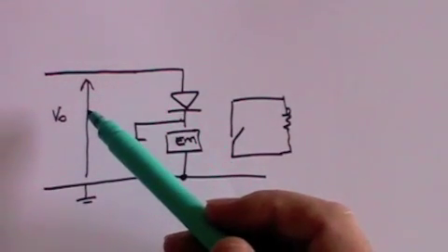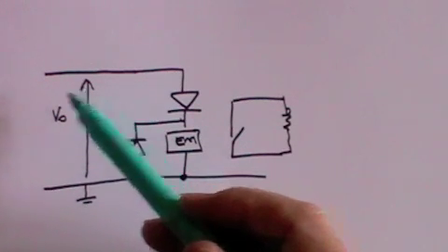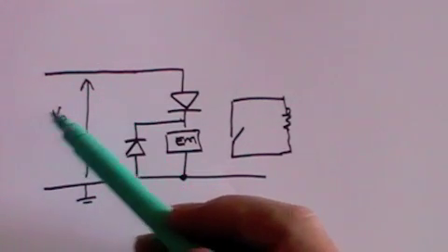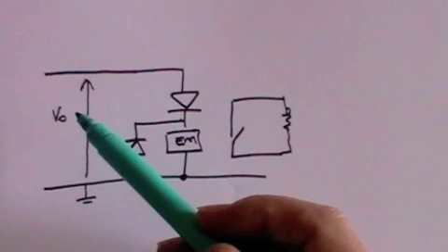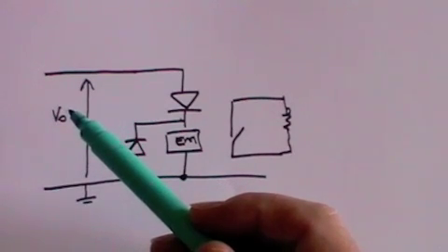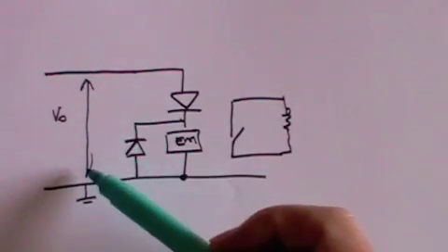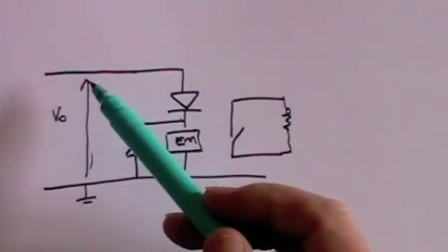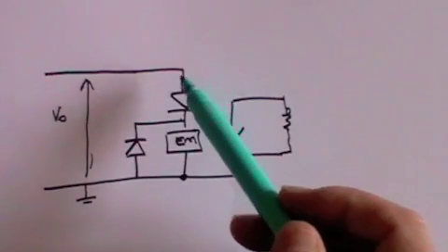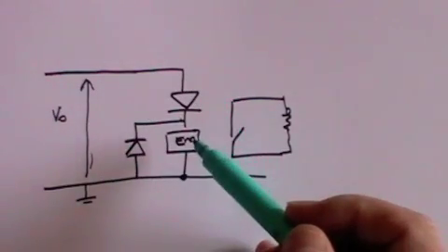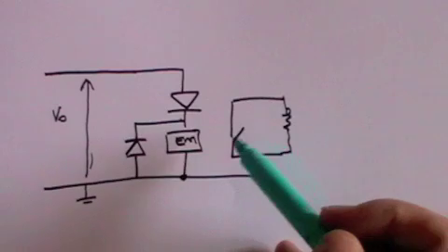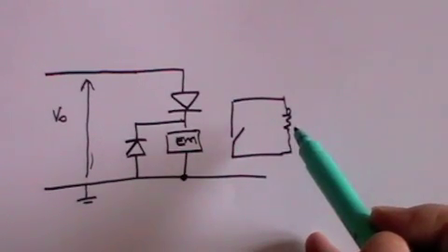But as soon as darkness comes and the room gets dark, then the sensing device will change its resistance such that the combination of that plus the operational amplifier and the circuitry reverses the polarity from a negative voltage to a positive voltage. As soon as you get a positive voltage, the current flows, the electromagnet then works and flips the switch and the light comes on.